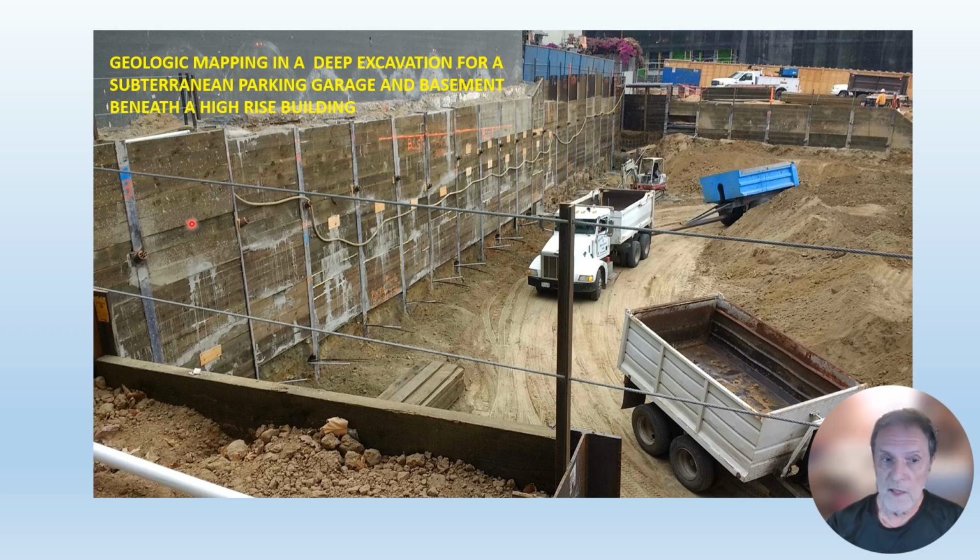So as the excavation proceeds down deeper and deeper, you put in wood lagging between these steel soldier beams, so that this whole excavated material behind this wall is supported.